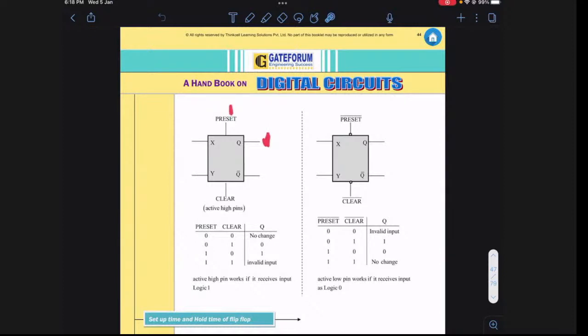If this is 1, that means this is 0. Okay, and if I want to initialize the initial state to 0, I'll be giving an activation signal on the clear pin because it's an active high pin. So I'll be making here 1. If I make here 1, you get here 0, and this is what your 1 is.